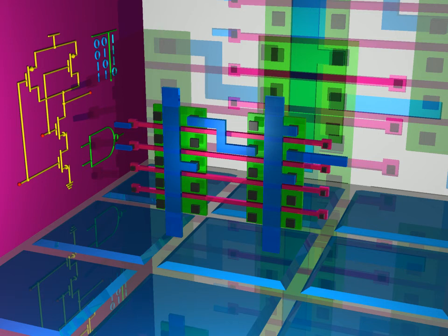The two red lines with metal attached are the NAND gate inputs A and B. The metal on the far right attached to the green area through a cut is the output of the NAND gate. The squiggly metal in the middle connects the two sets of transistors together and to the output of the NAND gate. With this information, you should be able to see how the mask layout matches the schematic.